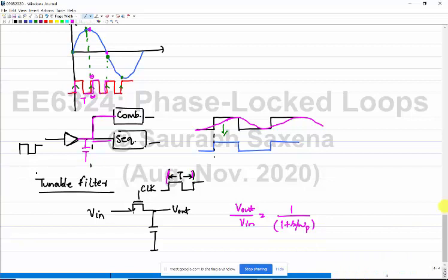Okay. So what I was talking about was a tunable filter, and in case of tunable filters, you use a clocked MOSFET to vary the filter bandwidth. The filter bandwidth is actually a function of the time period at which you are clocking the switch. So there also you need some kind of precise clock. Why do you use such kind of filters?